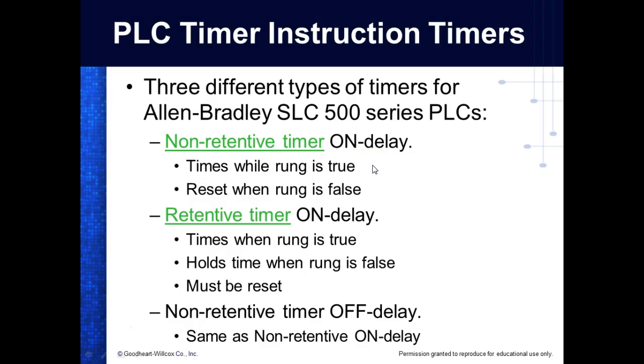3 different types of timers in Allen-Bradley 500. This is also true. We got a non-retentive on delay. We got a retentive on delay. And then we have a non-retentive off delay. So what would you think about the retentive? That means when you disable this sucker, it's going to hold its time. The only way you're going to do is we're going to have to pick up another output instruction called what? Reset. And we'll see that in a minute.